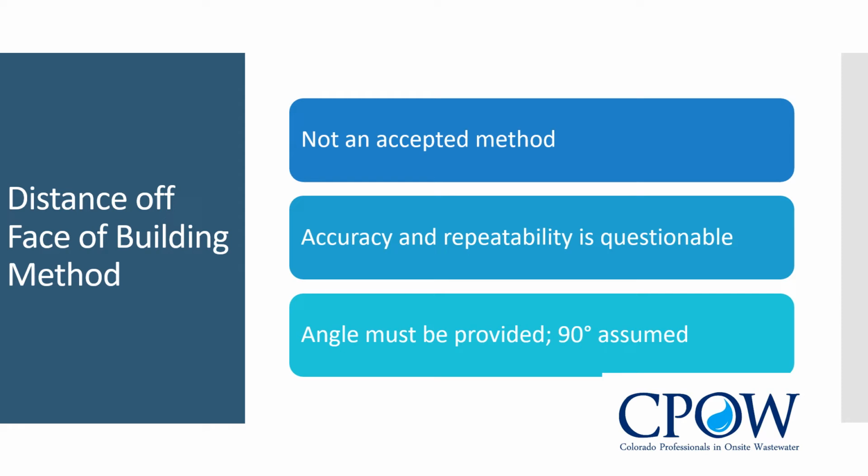Following a pipe is easy when it's exposed. Make sure your drawing makes it easy when it's buried. If you're following a pipe, you will likely need a bearing measurement, as this angle may not be 90 degrees from the face of the building.